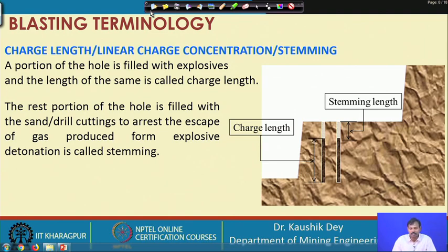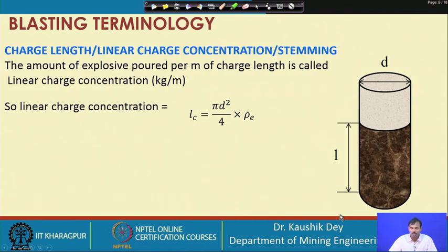Linear charge concentration is the term we use, which basically shows the length of charging of the hole, or the length of placing the explosive inside the hole. Linear charge concentration is the amount of explosive poured per meter of charge length.